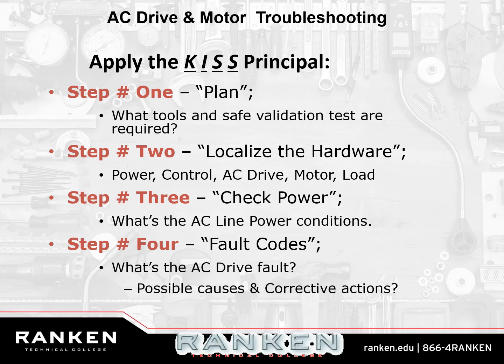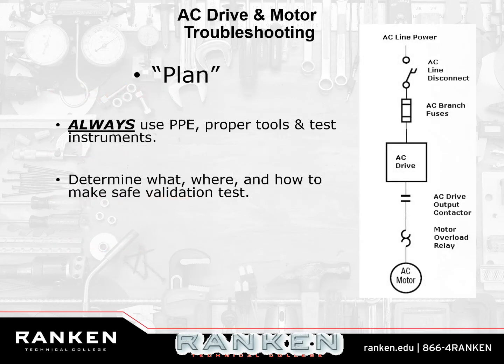It could be capacitive charging happening, or it could have just been a weird anomaly that the drive picked up on, and it never happens ever again. So you don't necessarily have to take them at face value. Sometimes there's an underlying issue or underlying cause.